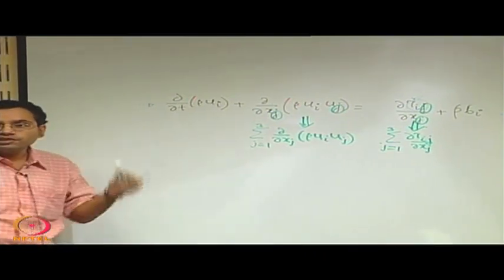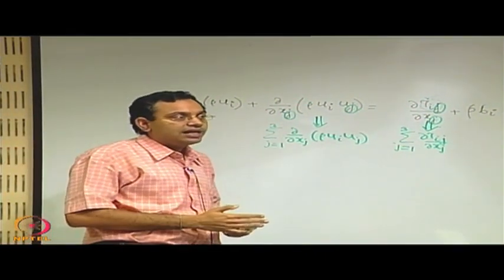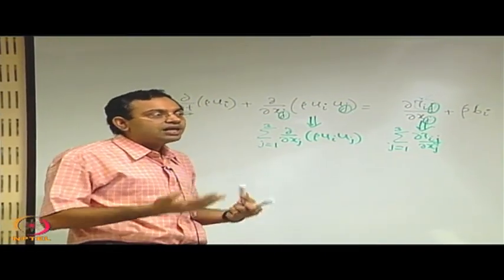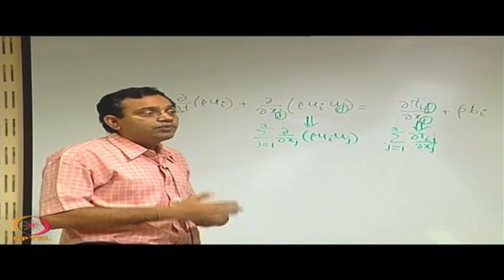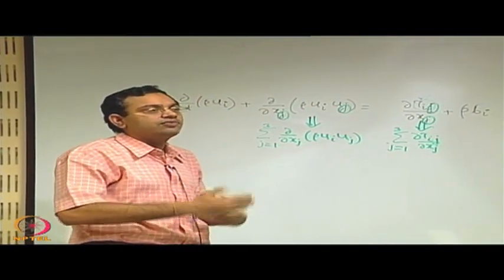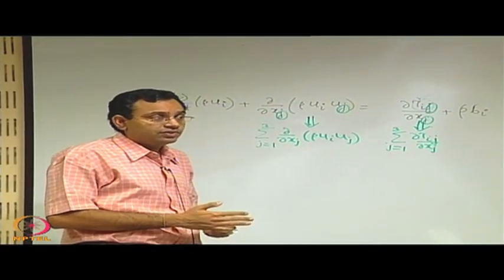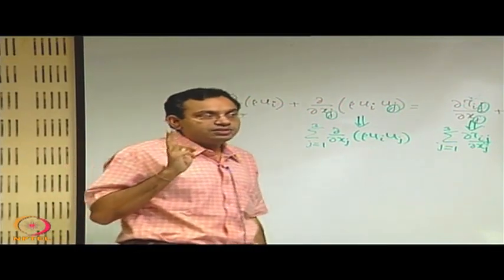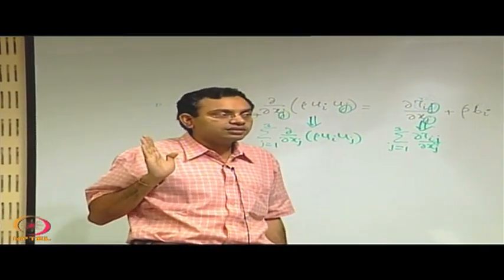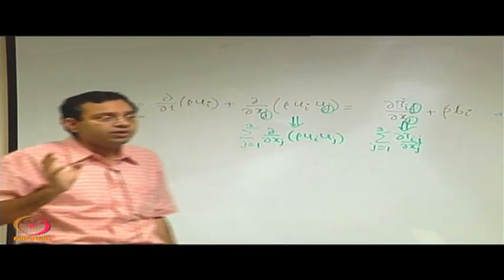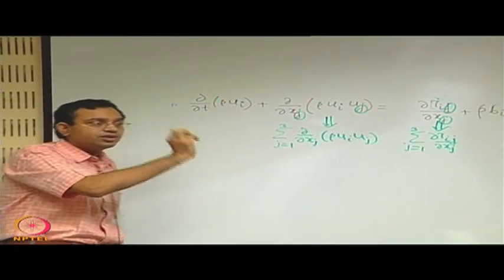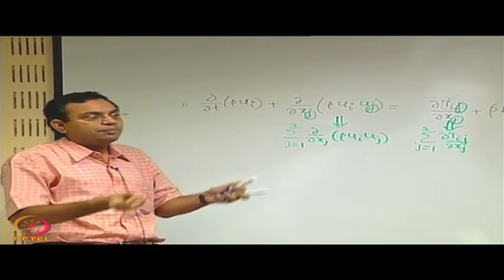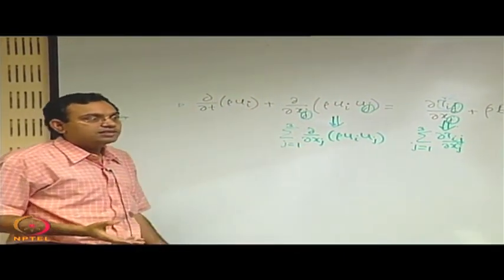That should be the pressure distribution, because we have seen what the hallmark of a fluid at rest is. If there is a fluid at rest, that means it is not deforming, and we know that fluids are in continuous deformation when subjected to shear forces. So, when a fluid is at rest, there are two important things occurring. One is there is no shear force, because if there is a shear force, it will start deforming, except for some special non-Newtonian fluids which we have discussed, but in general if you apply a force, the fluid will start its deformation.